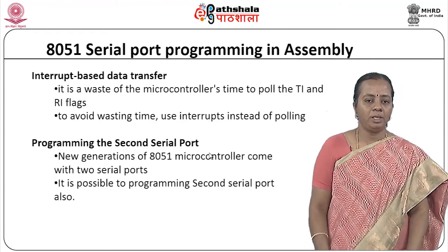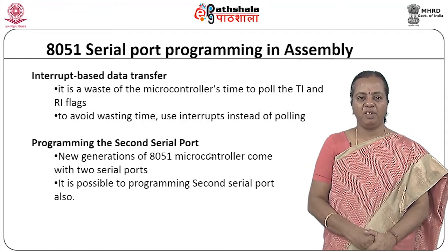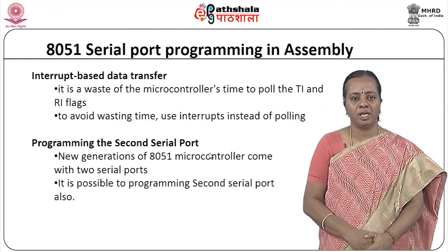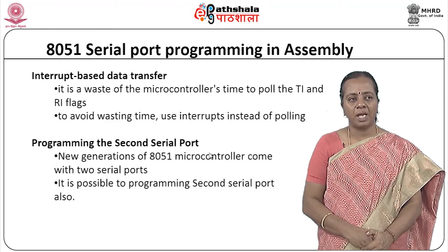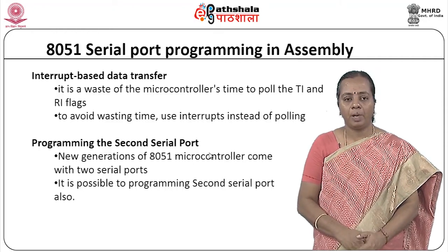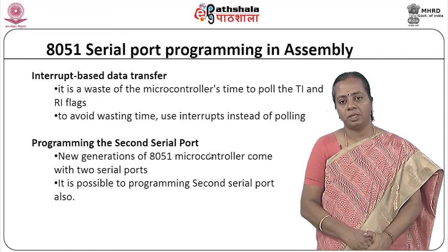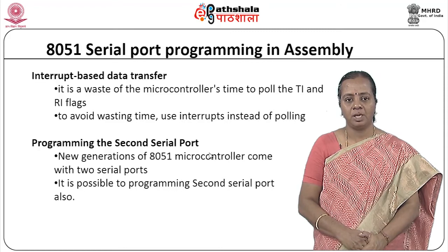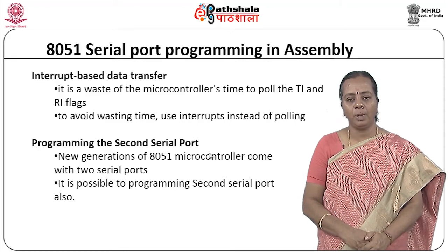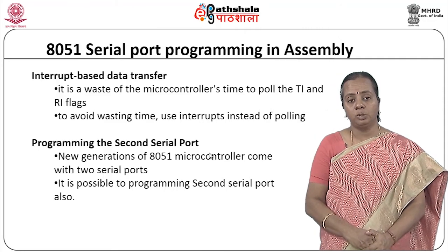So when you are looking at this kind of 8051 serial port programming, we will always be looking at whether TI is there, RI is there. Some time is wasted looking at all those things. This can be avoided by using interrupt based serial communication transfers. The new generation 8051 microcontrollers come with 2 serial ports.